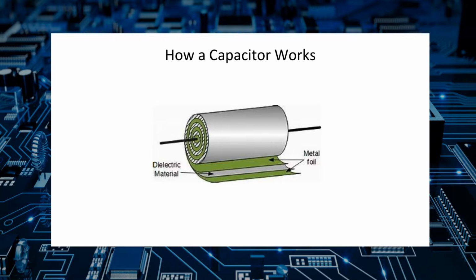In addition to capacitance value, every capacitor has a voltage rating. It's critically important that you don't exceed the rated voltage or the capacitor could fail. Sometimes capacitors, especially electrolytic ones, will fail short, and that can cause damage to the circuit, so it's really important to keep them within tolerance. Just like with resistors, a capacitor that's stressed beyond its rated value could fail catastrophically and explode.